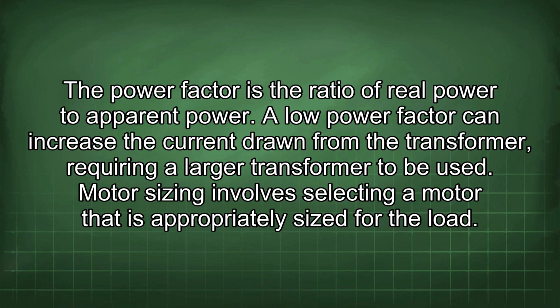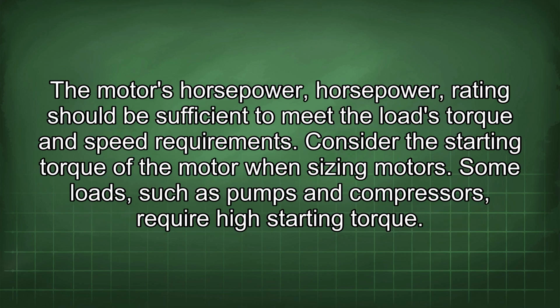Motor sizing involves selecting a motor that is appropriately sized for the load. The motor's horsepower rating should be sufficient to meet the load's torque and speed requirements. Consider the starting torque of the motor when sizing motors. Some loads, such as pumps and compressors, require high starting torque.